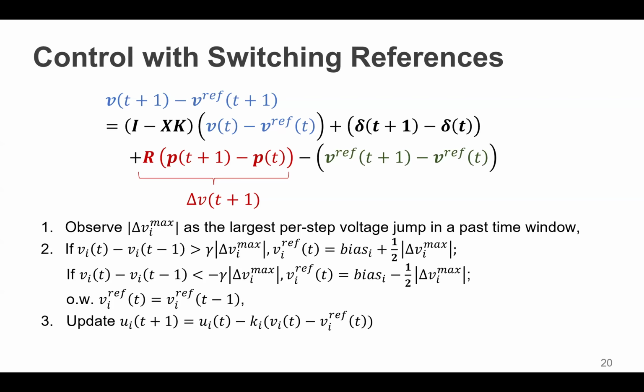How do you get that? So for the analysis, we are not dependent on the exact form of the error. We just take this error into account to analyze the convergence of the voltage. For the convergence of voltage, we can see the impact of this term here. But you should have some assumption on delta, right? Like bounded or something. Right, exactly. We will show input-to-state stability, so we require the bounded errors for the bounded voltage deviation.